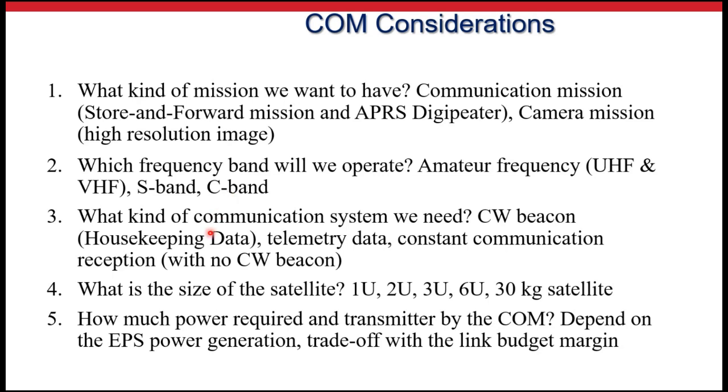And then what kind of communication system we need. I think this is not really important, but this is for your information. Let's say you would like to send in terms of what protocol, so what communication system is suitable to use that kind of protocol. Okay, again, the fourth one, the size of the satellite. Is it feasible to use that kind of camera with that size of lens on board 1U? Or is it feasible for only 3U and above, right? So this depends on our design and needs to be considered.